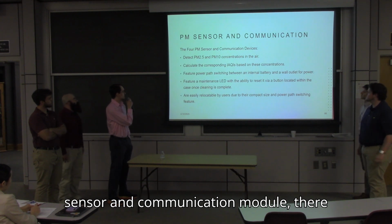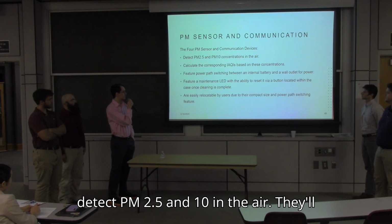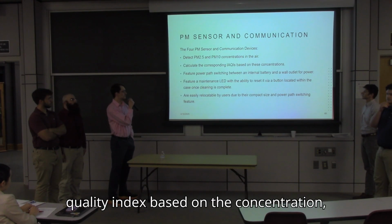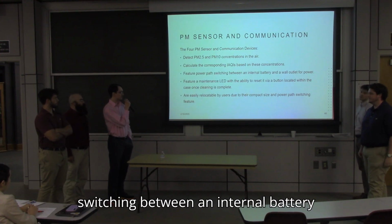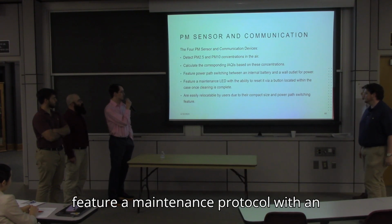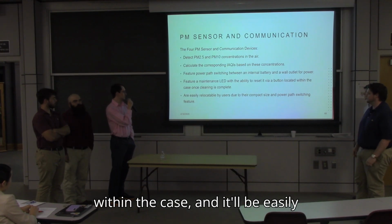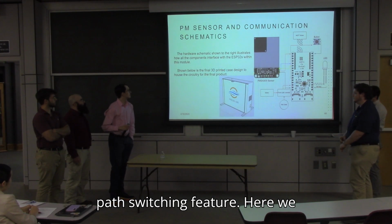So for the PM sensor and communication module, there will be 4 devices, and they will detect PM 2.5 and 10 in the air. They'll calculate the corresponding indoor air quality index based on the concentration. It will feature power path switching between an internal battery and a wall outlet for power. It'll also feature a maintenance protocol with an LED, to reset it via a button located within the case. And they'll be easily relocatable due to their compact size and power path switching feature.